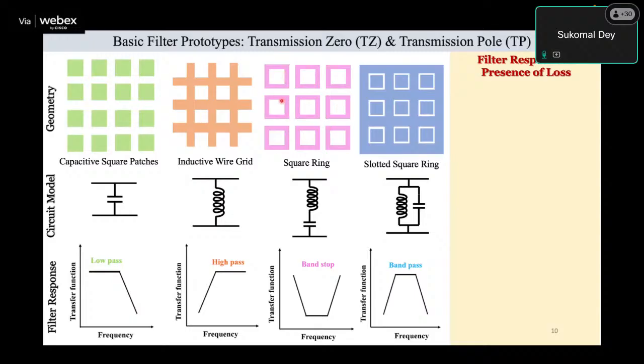Now in the third and fourth case, suppose I take the example of the third case, where you are making a simple metallic array like this. First, what are you doing? You are basically designing the single resonator, then you apply it in an EM simulator to simulate it with the help of a Floquet port.